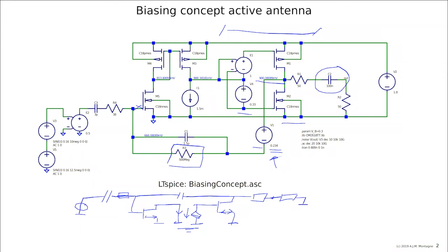Because at this level, we don't expect any change, except, for example, for this 500 mega ohm resistor, which is of course noisy, and its equivalent noise source can be drawn like this, a current in parallel. It can be split to the output of the amplifier, which is then in parallel with another. You can forget about it, but it is a current source in parallel with the input. So then we can omit it.